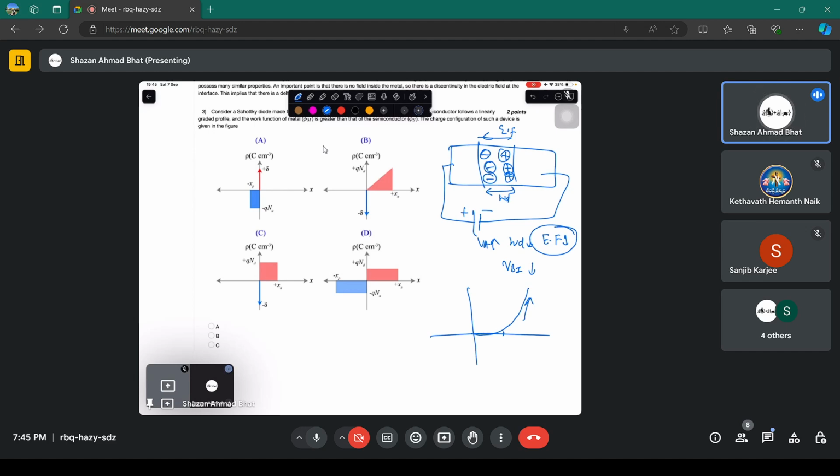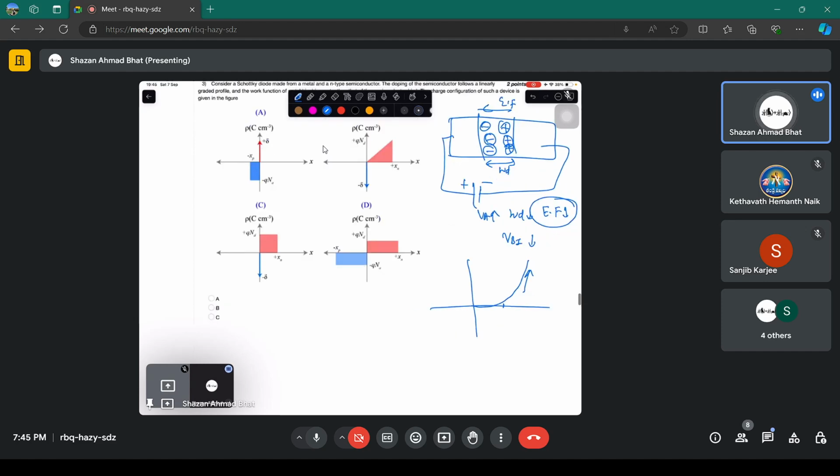Okay, that is the very misconception. The built-in voltage, which is 0.7 for a diode, is not measured externally by probing it. You cannot probe it with an external device. If you connect a meter to a diode, it does not measure 0.7, it measures zero. Why? Because the current is not flowing. The built-in voltage is internal to that diode, but you cannot measure it.